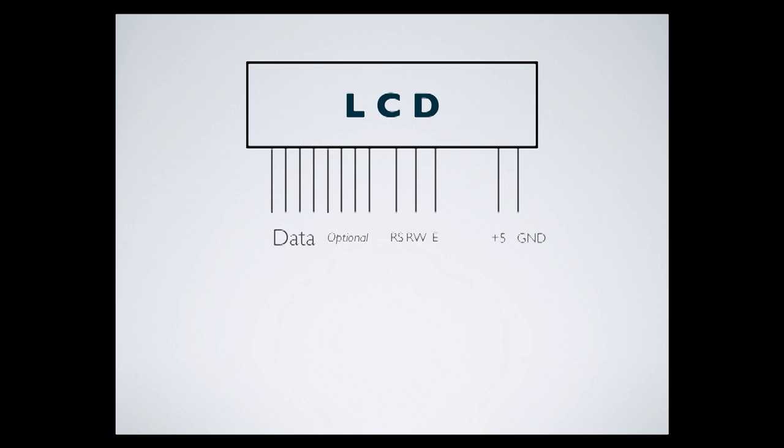So by using this LCD on the Arduino Uno, you've used up all your digital inputs or outputs with this one LCD display. In fact, you couldn't add much more to it other than the analog inputs or outputs if you attached an 8-bit display. Now, we only used 4 bits: 4 data, RS, RW, and E. That's 7 of the 11, so that would leave you with 4 additional digital pins to do something with. You can see how quickly you can use up resources on an Arduino.